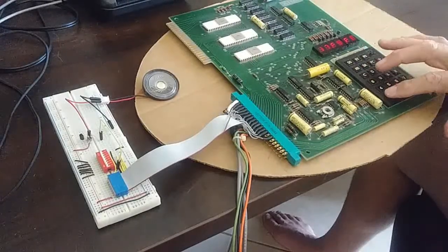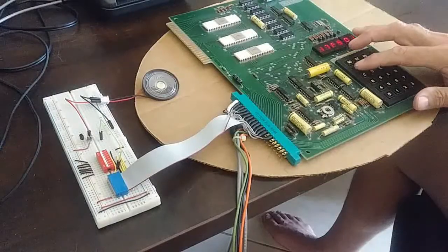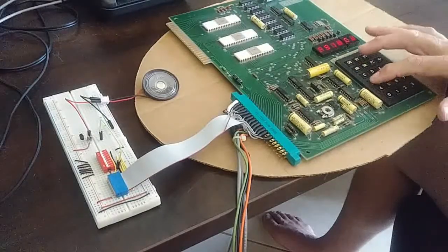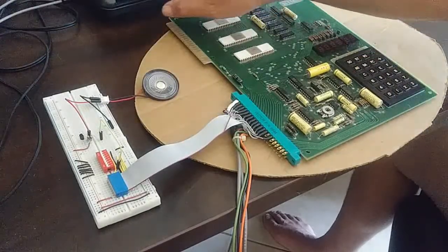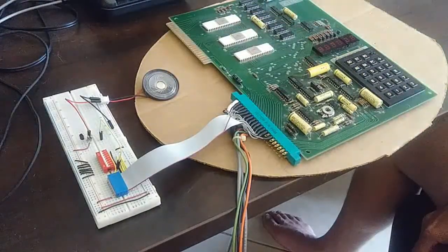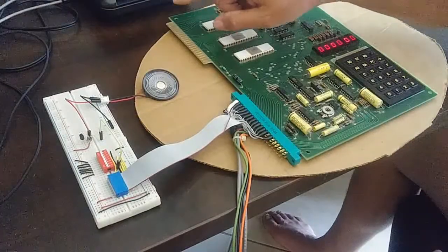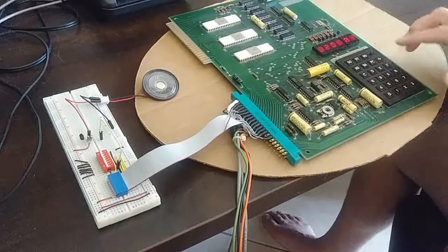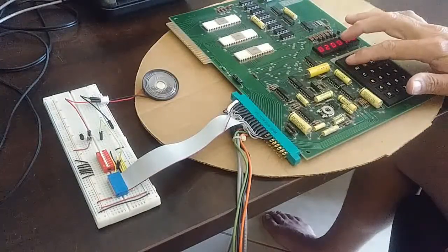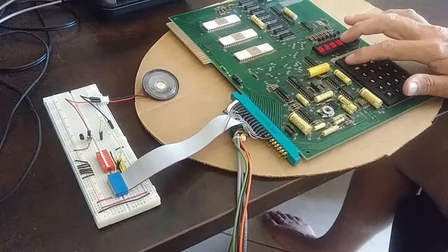So we're going to put that to 01, and then finally we're going to go to address 1873 and press go and play on our tape. And we'll load that program back into our KIM-1. There we go. Stop. And then we'll go to address 0200, our starting address. There's our A0. Let's press go and see what happens.